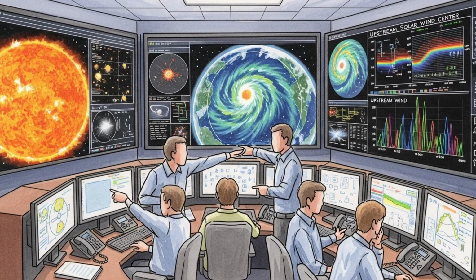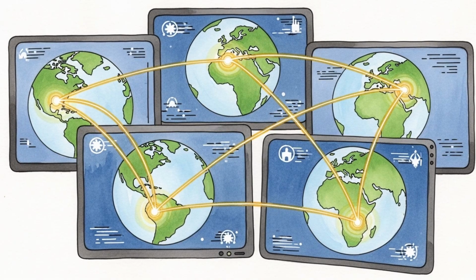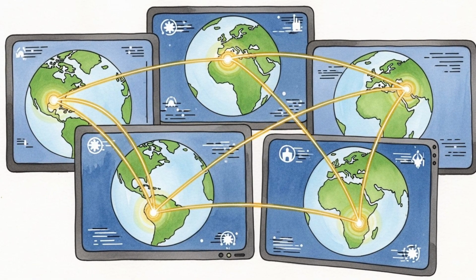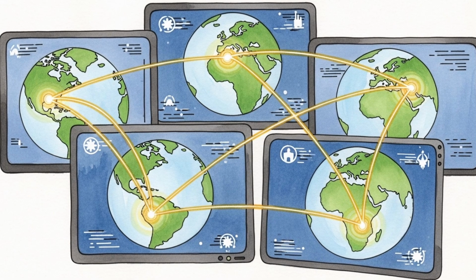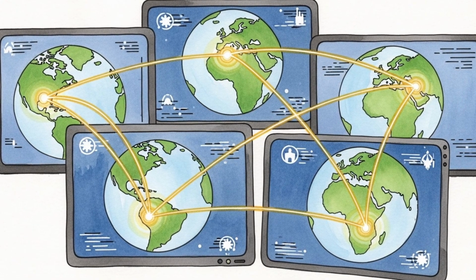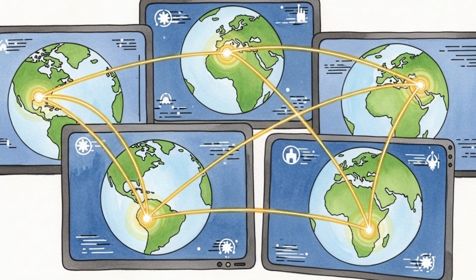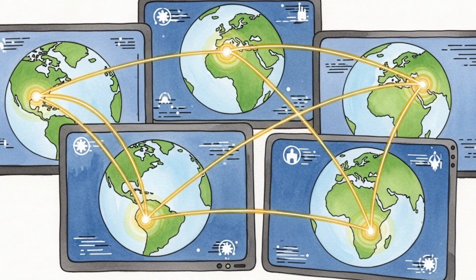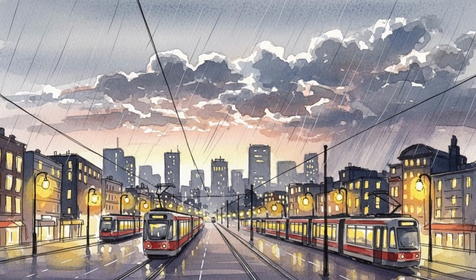They pre-plan orbit determination with higher cadence and reserve fuel for altitude maintenance in low Earth orbit. They set communication schedules with more passes and flexible data rates. They confirm that ground stations have redundant paths and can switch modulation and coding quickly. During a storm, procedures are simple and conservative.